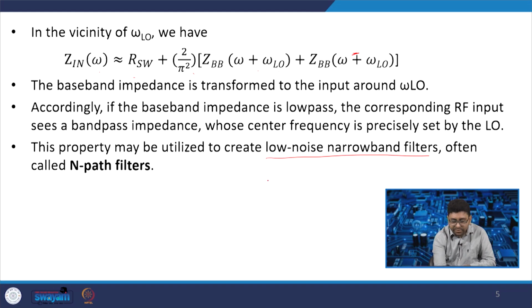At RF frequency, Q is inversely proportional to the bandwidth, and if we want to realize the filter with inductors or other active components, it will consume high power, or the Q requirement of the inductor is very high.